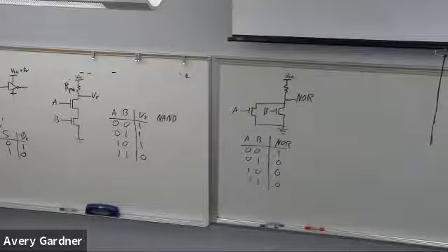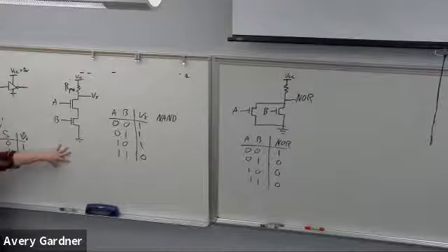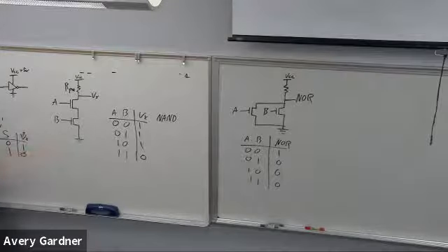Okay, so let's take a moment and think. We've used 3-input AND gates multiple times. How would I add a third input to this one? Another one in series. Yes, just add C in series. If I had a third input, A, B, and C, then I would need all 3 to be on in order for the current to flow and therefore go to 0.